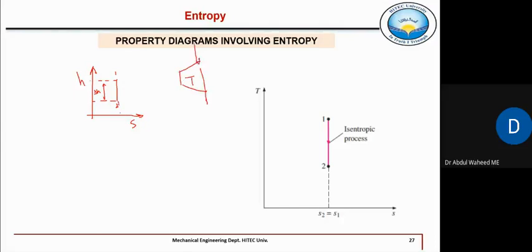In a turbine, here is H1, here is H2, and work is done. So if it is fully isentropic, then from 1 to 2, entropy remains constant, S1 is equal to S2, but enthalpy changes, because this enthalpy change, H2 minus H1, is actually equal to work done. And we multiply by the mass, because a certain amount of mass is entering and leaving. So enthalpy is changing.